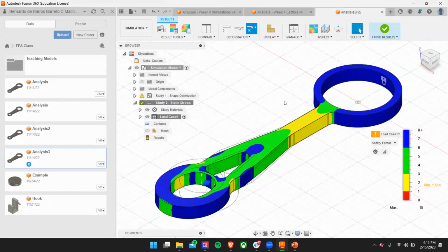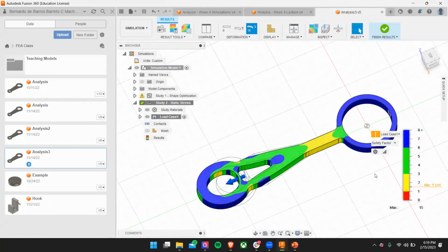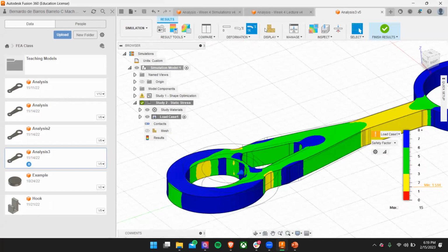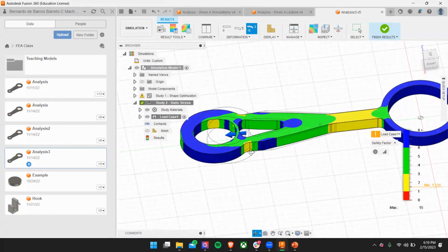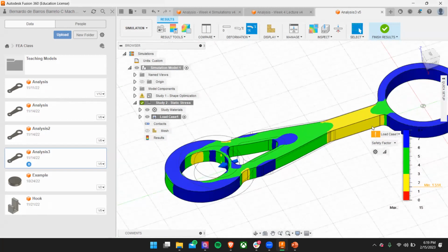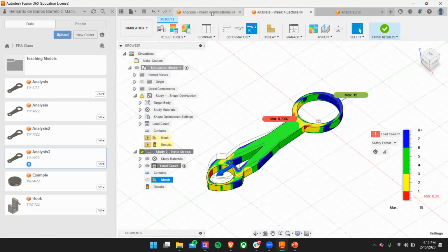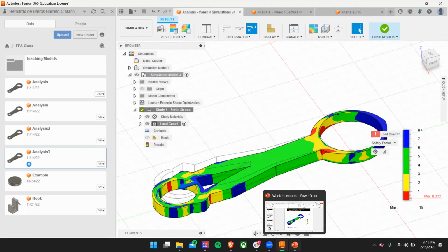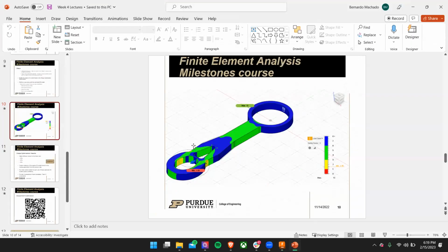And then when I did the class, this was the one I did. As you can see, this one was above 1, mainly due to the fact that I did not remove as much material. I also filleted some of these things, which, like we have said a couple of times, can definitely change the way force is applied on those corners. So that's basically what shape optimization is.